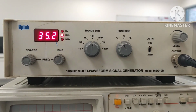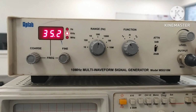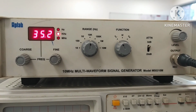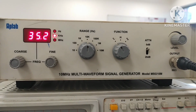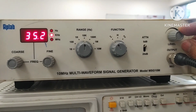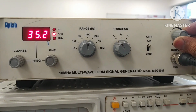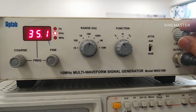The fifth knob of the function generator is level. It means we can change the amplitude of the signal with this level. In simple words, we can change the peak-to-peak voltage of the signal with the help of this knob. If we rotate this knob anti-clockwise, the peak-to-peak voltage of the signal decreases. If we rotate it clockwise, the voltage of the signal increases.